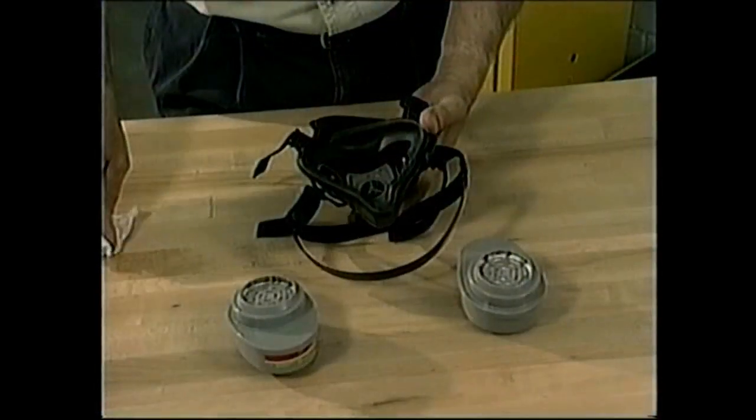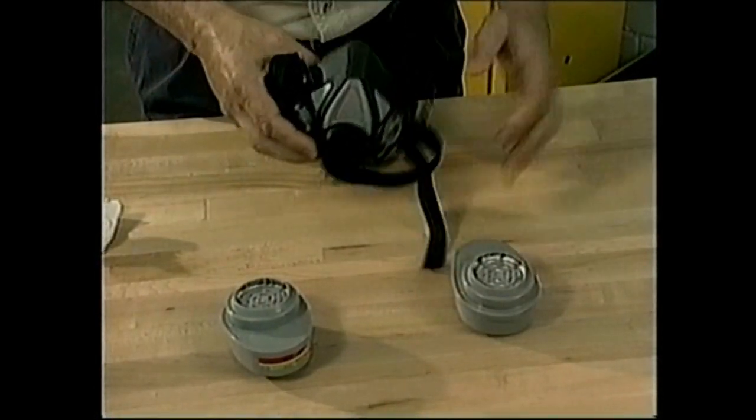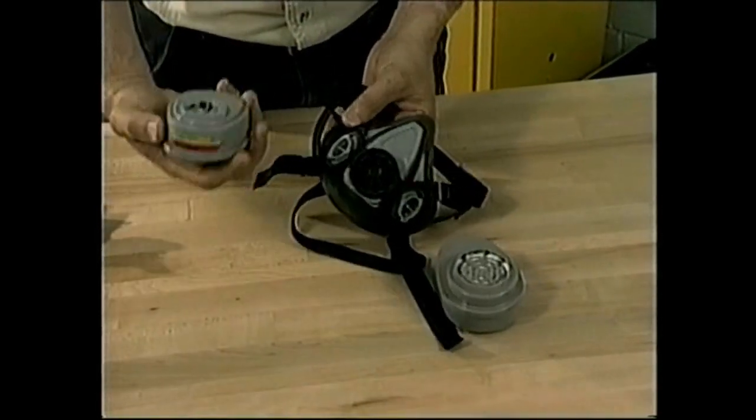Because air purifying respirators have many components, you need to carefully inspect, clean, and store your respirator. But maintenance procedures often differ depending on how long you use your respirator and what contaminants are involved. Your employer will tell you what the maintenance requirements are in your workplace. Some respirators need to be cleaned after each use. For occasional use respirators, a daily wipe down may be sufficient.